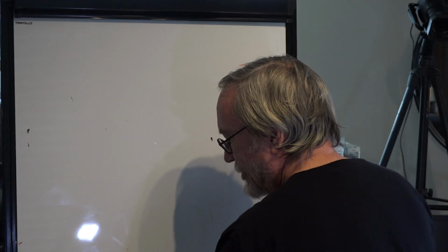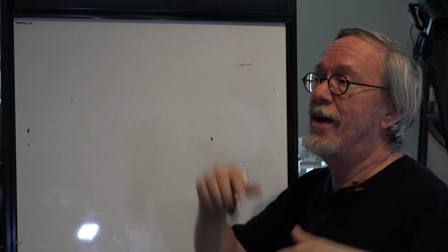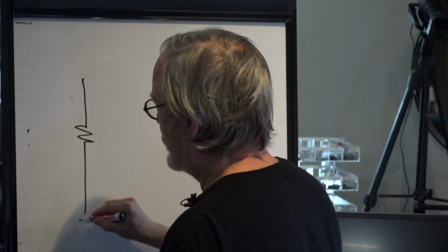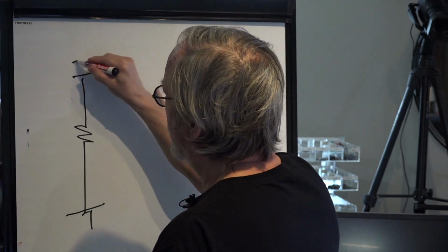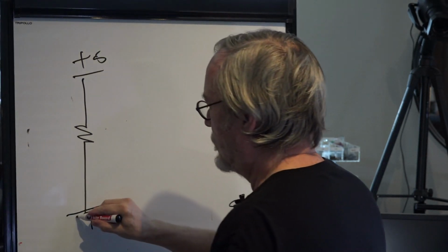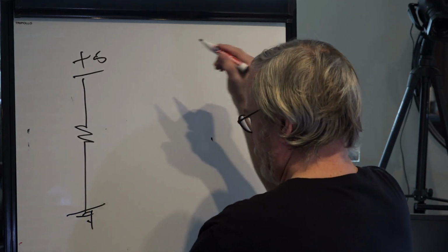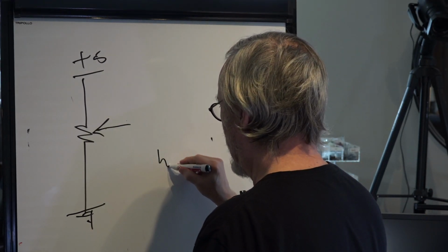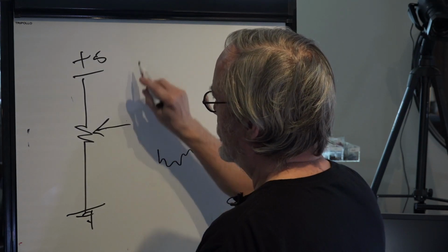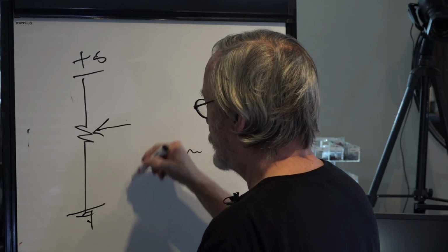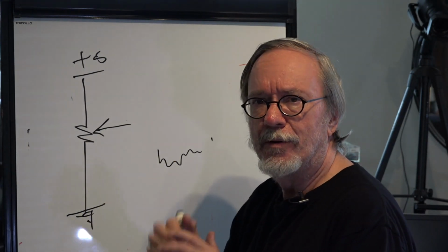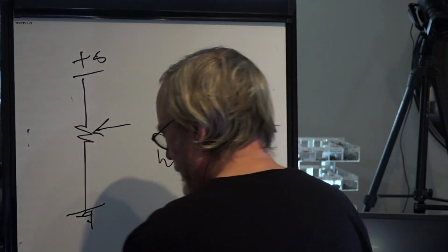And we're gonna find that that pot has got way too much reach. Why? Because, to keep things simple, I went all the way from +5 down to the ground. You can see I draw my grounds really round. Cool. Where's the video? It's down here. What happens when it's way higher? Nothing. When it's way lower? Nothing. So it's going to be a range on that pot that's ridiculous. But we're just experimenting now, so that's okay.